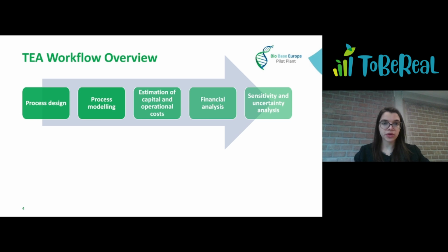So just a general workflow overview of how a TEA is performed. We initiate with a process design where we define all the unit operations, all the equipment that is necessary for each step of your process, which then will lead us to a process modeling, where we do a process simulation using a commercial process simulator software, such as SuperPro Designer. And there we can include all the unit operations and the streams in between them.